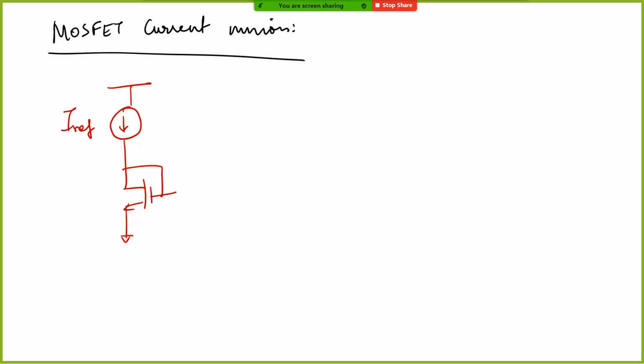It is just the nomenclature which is stuck on from the BJT days. So unlike a BJT where a physical diode is actually formed, here you do not have one. Of course the parasitic diodes are there, but they don't come into the picture when the MOSFET is in operation. So this is just the nomenclature.